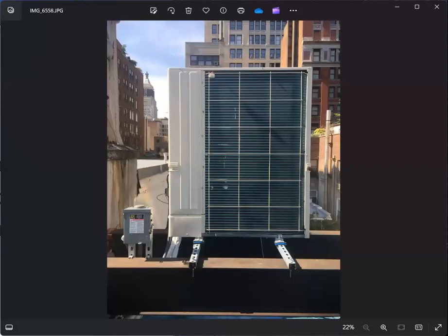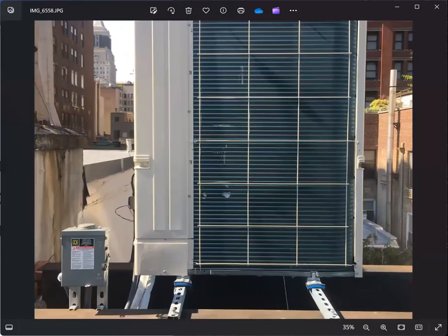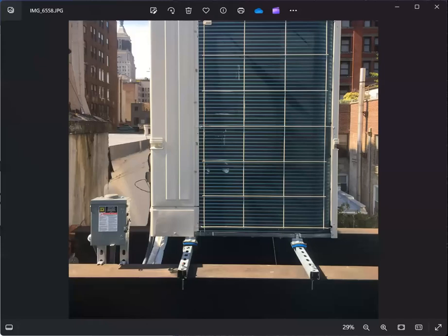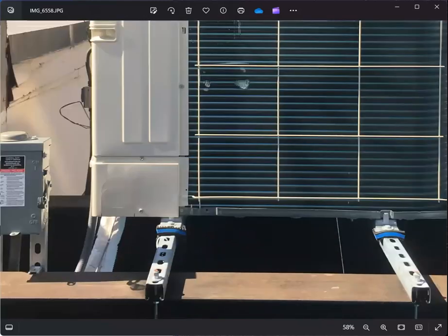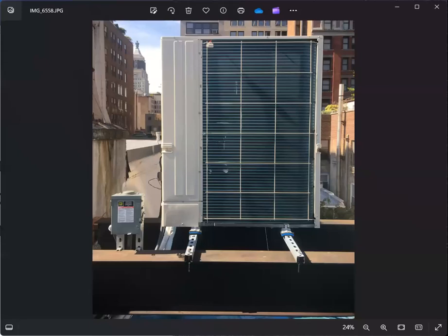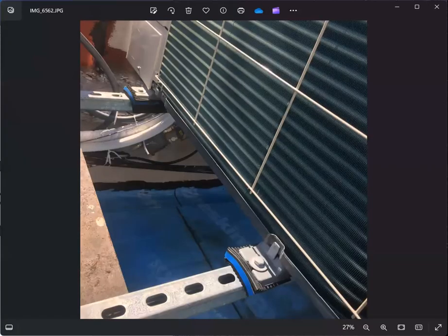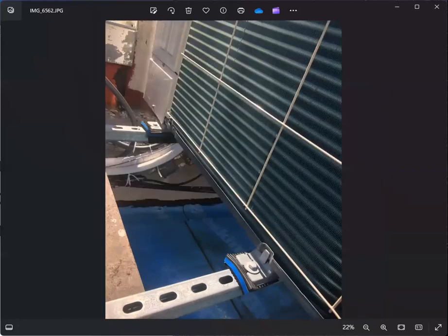And this is the condenser, I mean the condenser for the AC units. So we have a split system. Just make sure to identify the model number also, and you need to have the breaker for this equipment. Make sure that it was anchored properly so that it will not tilt over during high wind, because it's exposed on the outside. Make sure that it has vibration absorption rubber also.